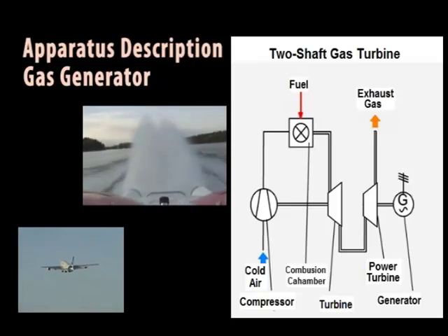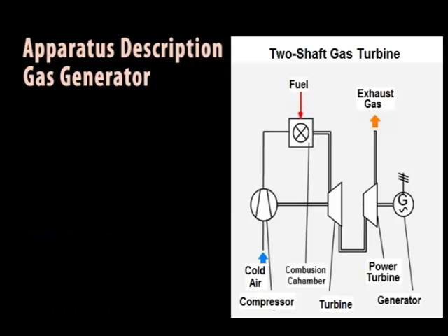As the first turbine, together with the compressor and the combustion chamber, only generates the working gas for the power turbine, this group of components is also called the gas generator. This consists of a radial turbine with a directly coupled radial compressor and combustion chamber. The turbine and the compressor, together with the bearing housing in between, form a compact unit. This unit is normally used as a turbocharger on turbocharged engines.